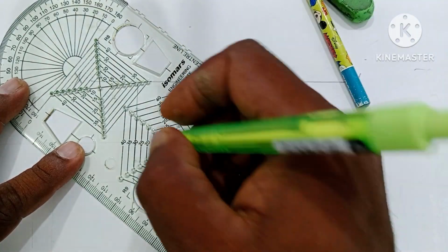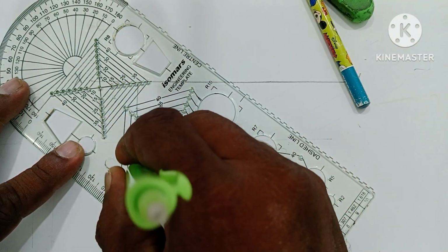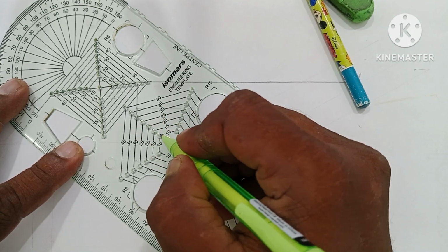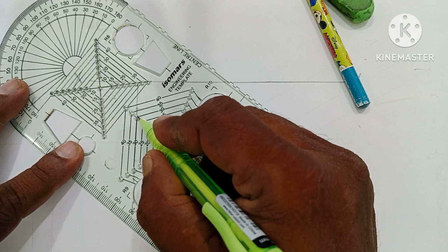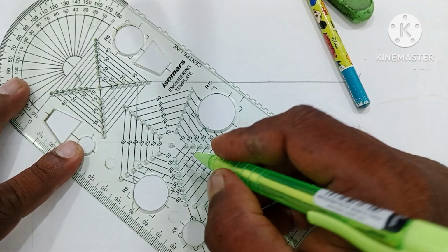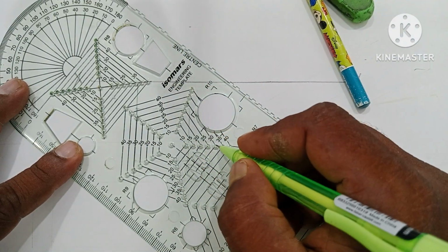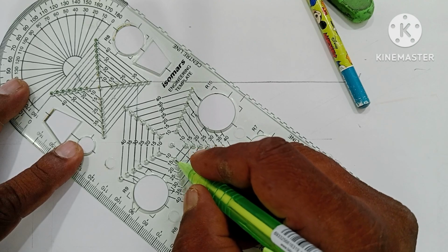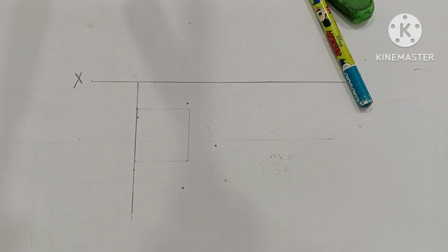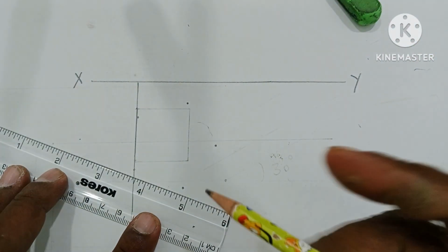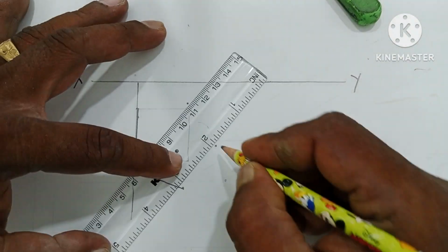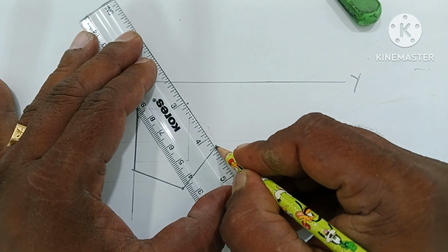And you can locate all the corners, starting from the first 10 mm, which corresponds to 30 mm: 1, 2, 3, 4, the fifth hole is the 30 mm side. Similarly, trace it for the other corners. Put a dot using a micro tip pencil at each: 1, 2, 3, 4, 5. So remove your template and using a drafter scale or an ordinary scale, you can join all those located points so that you will get a pentagon of side 30 mm.